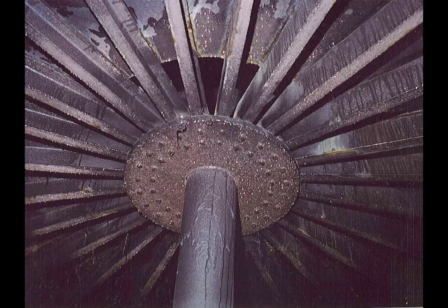You'll get a better look at things like the structure of the reservoir. This is actually the top portion of a steel tank. And that plate you see there is often called a dollar plate, and basically it is a way to transfer the load from the individual rafters that you see coming on top of that plate to the center column, which is what you're seeing, a center column in one of these steel tanks that all the roof rafters land on to provide the structural support for the roof.